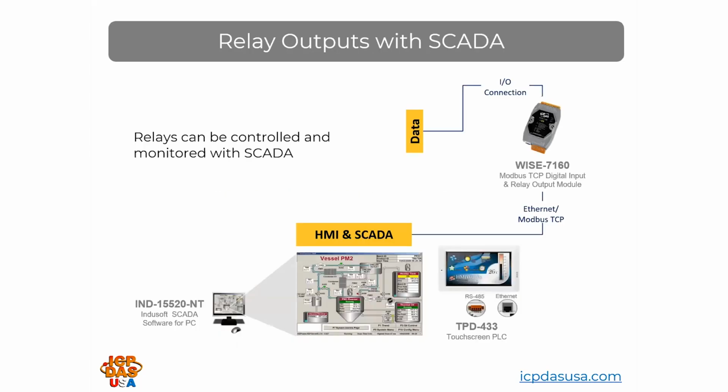In addition to the daughter board type of I/O equipment for the relay outputs and the solid state outputs, we also provide remote I/O, and we also have configurable I/O that can be set up to trigger outputs based on inputs. They communicate over different protocols. This one is a WISE 7160, communicates over Modbus TCP, so you can use it with SCADA software like shown here. So you can have buttons set up on the screen in the SCADA software or show different measurement levels for different equipment attached to the terminal block sensors.